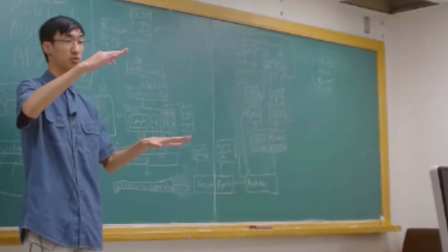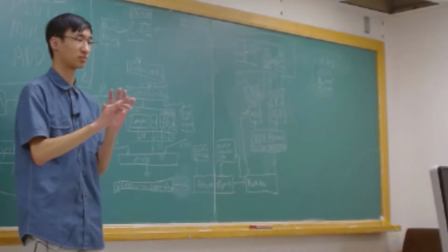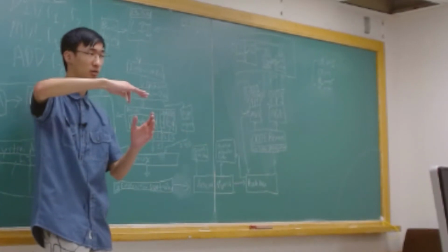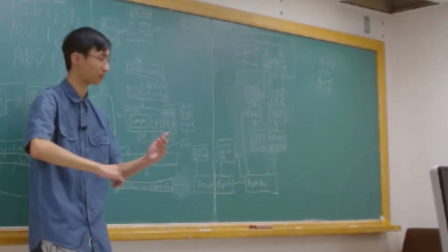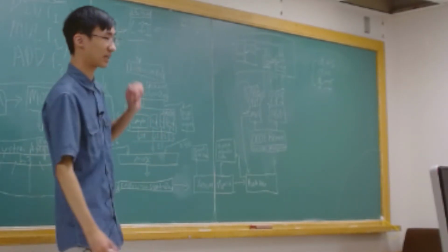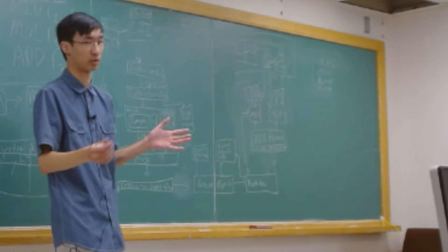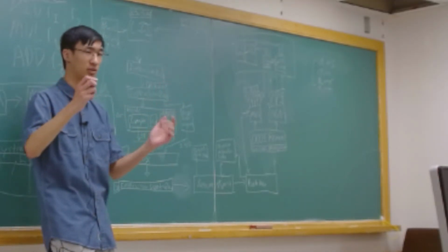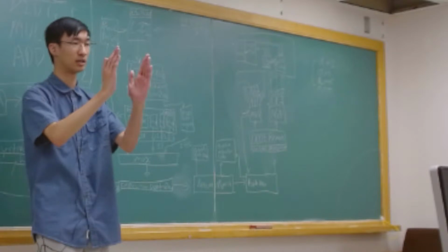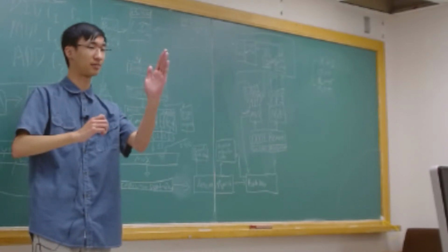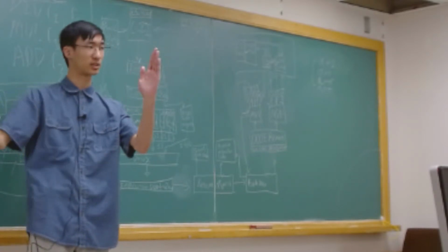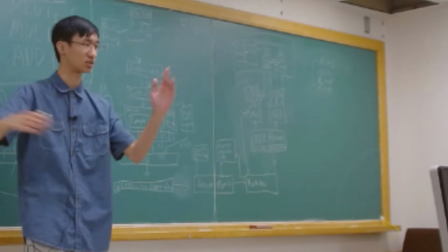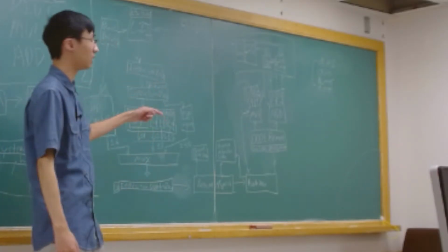And if you get it wrong and you do take it, or actually it doesn't matter, sorry. Whether or not you get it wrong, you'll increase it or decrease it depending on whether you take or don't take. And so that's the saturating counter, but we found out very quickly that the saturating counter wasn't enough for complex patterns, because you could get a pattern where you'd be like, okay, so I'm going to take it. And then the pattern says don't take it, so you subtract.